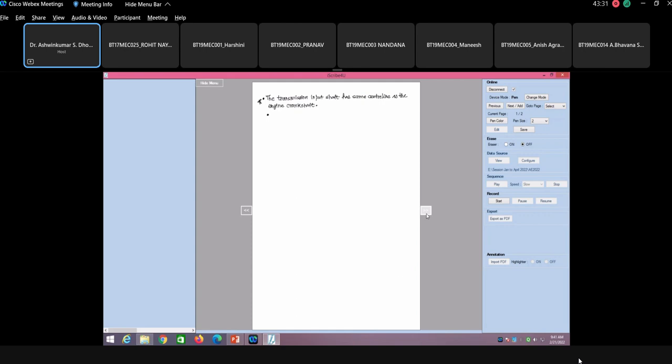That means if a pulley moves even slightly forward or backward, then understand, sir, that if you are getting a life of 50,000 kilometers from the belt, it will drastically reduce to, let us say, 20,000 kilometers, because all the time it is going to get subjected to some kind of unknown loading for which it is not designed.